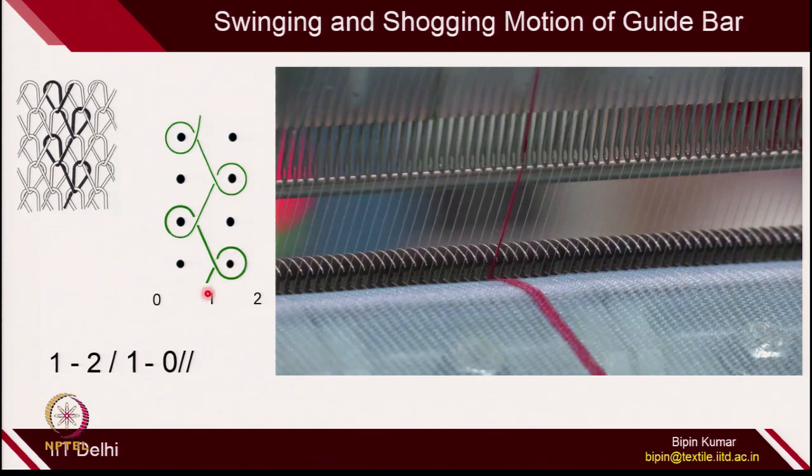So, this is what is shown as a lapping diagram, where you can easily find out this is 1 cross 1 tricot in a closed loop construction. It is a closed loop construction because the direction of overlap and the next underlap are in opposite directions.